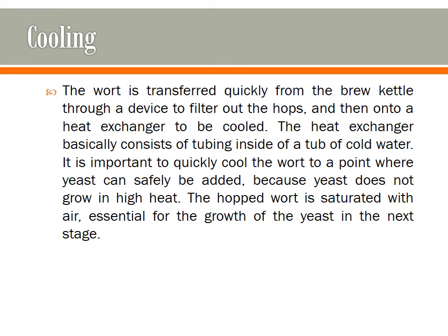Now here in the cooling process, the wort is transferred quickly from the brew kettle through a device to filter out the hops, and then onto a heat exchanger to be cooled. So the cooling process takes place in a place called heat exchanger. So this heat exchanger consists of tubing inside of a tube of cold water. That's where the cooling part comes.